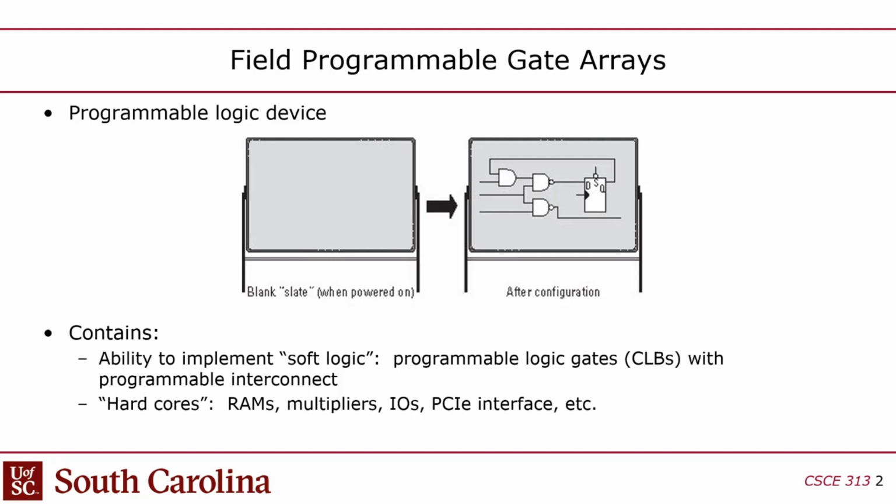It's kind of like that TMS thing that JTAG uses. It's a specific bit pattern that makes it do different things. If you just put a 0 or 1, it just acts like a reset. But if you put a high-speed pulse, like a bit stream, in there, if you know the protocol, which I don't even think is an open protocol, that's why you have to buy their debugger.